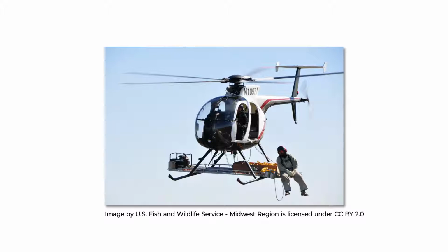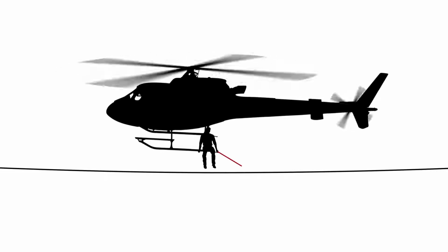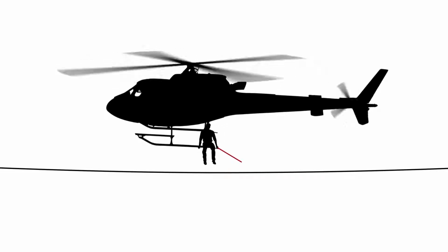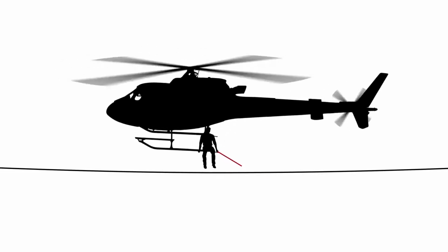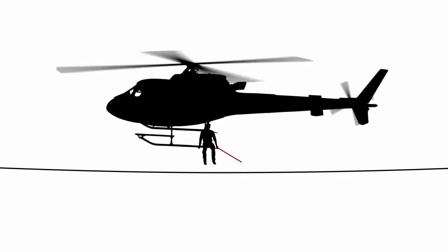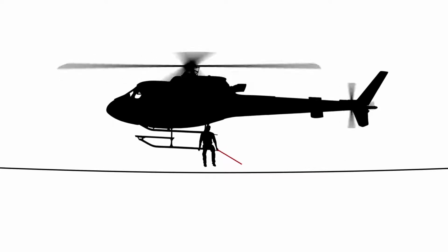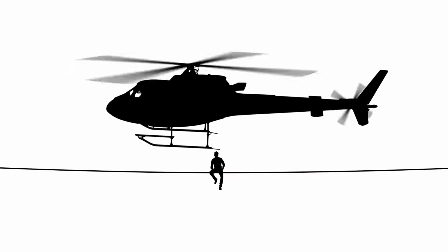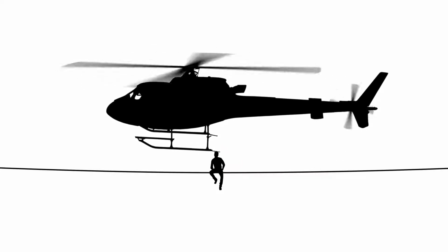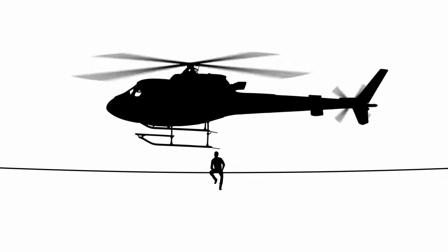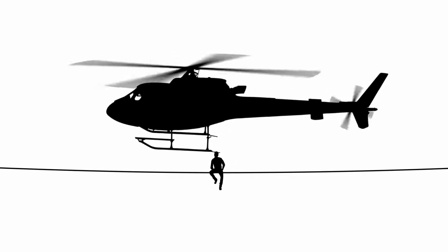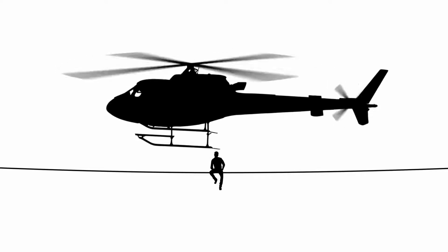Now, this one is also interesting. As he approaches the high voltage line, the man has a pole that's used to charge the helicopter to the voltage of the line. When the lineman reaches a certain distance from the line, current will start flowing, and the current will stop flowing through the sparks once the helicopter is at the same potential as the line. And now it's safe for him to remain on the line and attach himself to the line. So if the power line were instead near the ground, you certainly wouldn't want to get very close to the line, and I would leave a good margin of safety.